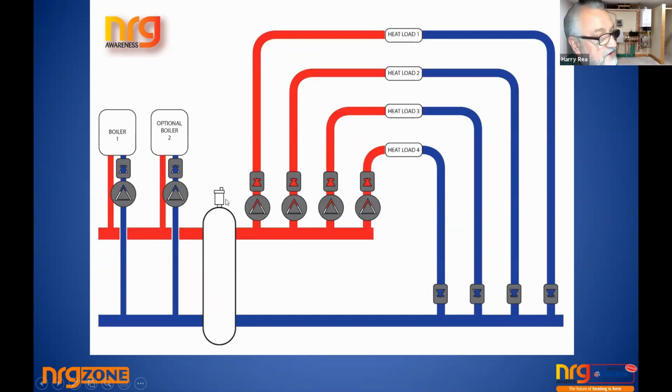So in this scenario where people use low loss headers, everyone would reckon that it's the panacea of all heating problems, because it has deaeration, it catches dirt, you have a drain point at the end. But there is a few issues that I'd like to talk about on that again. But you do, of course, have the situation where you have an open bypass, the water can flow back to the boiler. So it's just another way of doing it, but you've given yourself a relief on the water circulation back here that can slow the water down, which is a great idea.